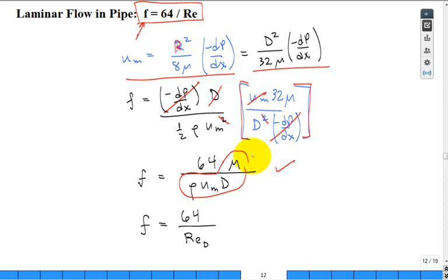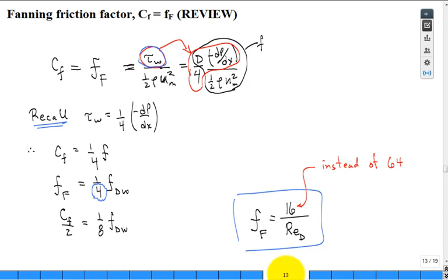Can I use that, Professor, for maybe a Reynolds number of 20,000? Nope, only below 2,300, and only after it's been fully developed. Now, I am so glad that nobody that I know of uses a Reynolds number for internal flow in a pipe where the characteristic length is the radius. Oh, there's probably somebody out there in the world. I haven't seen them yet.